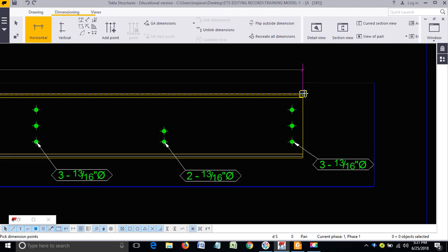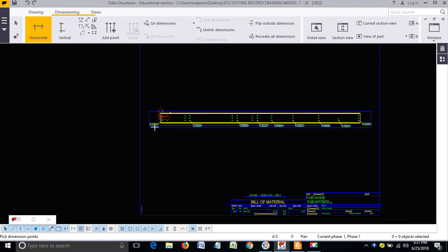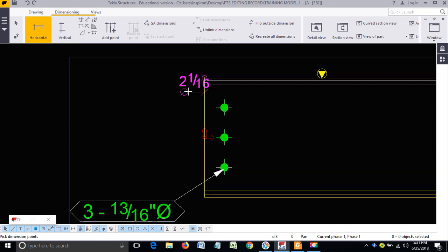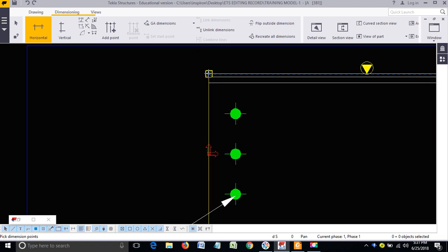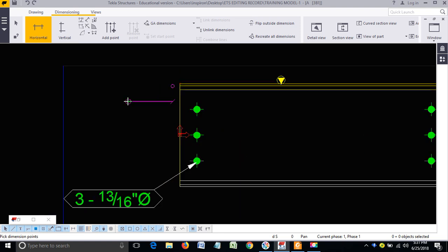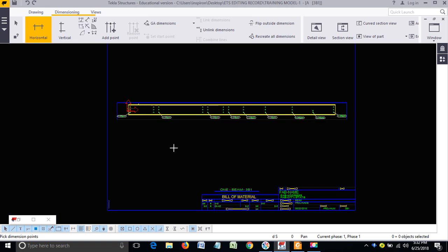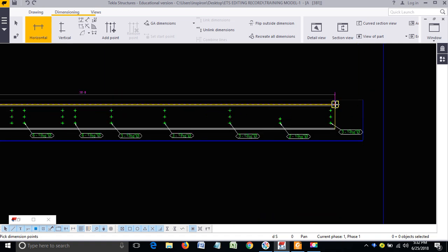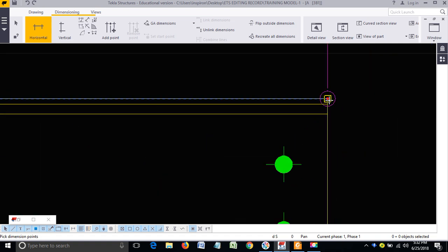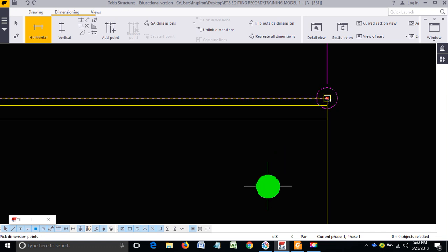I will tell you a simple tip. When you pick the left side, just take the first point and pick it. Now the requirement is that we have to go to the right side end, so zoom out, show the cursor where you want to go, and simply zoom in. In one shot you came here suddenly, clear, and pick it.